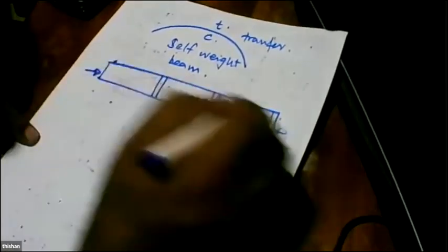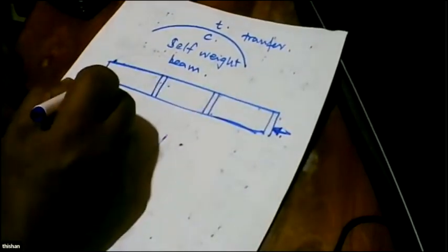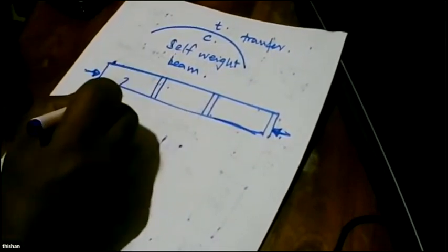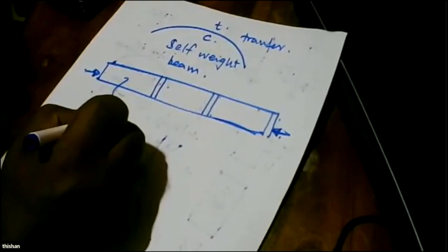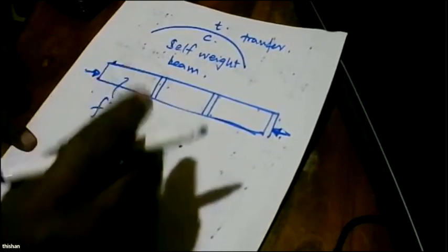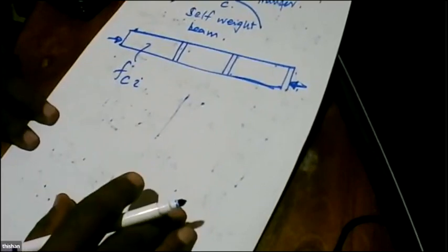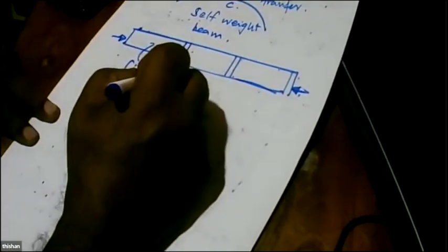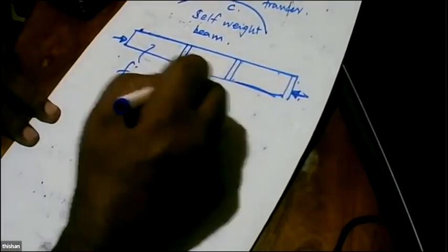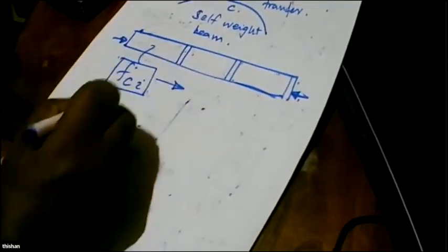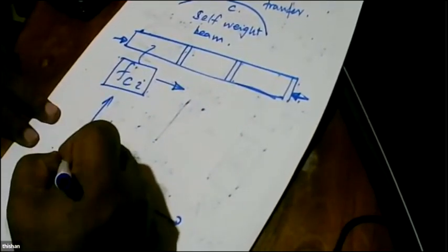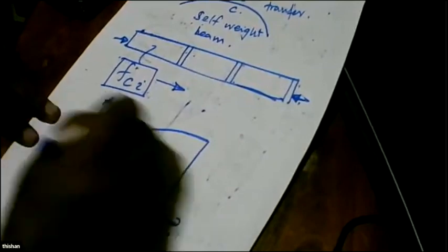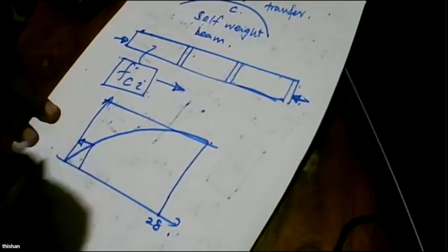And what happens is, we cut the wires after concrete has gained strength, but concrete has not gained all its strength. So that is the initial strength of concrete. We have to allow some compression, but we are in the strength development curve of concrete, and after 28 days we might get good strength, but we are here, somewhere here.